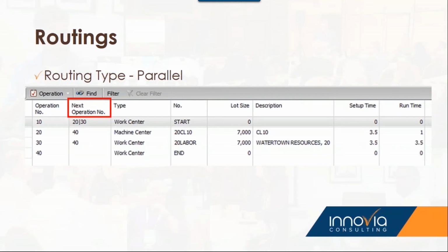There are some tips with that. Obviously, you don't want your labor to be a constraint. You want the machine, because the first operation you list should be your primary constraint. You're trying to manage the machine time, the work in that work center, not so much the people. But for one customer, we set up the machine, and then we need a setup person for 1 hour, and then we need three people to run the machine for the next 4 hours. You can do that, and that could be reflected in your cost rollup.